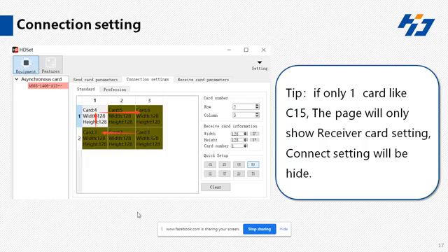As you can see, there is a quick setup, and quick setup four is clicked over here. This means that the first receiving card is on my right-hand side at the bottom, and the second receiving card is moving towards the left of the first receiving card, and then above it is the third, then the fourth receiving card, and after the fourth it is the fifth and sixth. So it is very easy to figure out how you have connected. Just assume you are in front of the screen, or just assume you are at the back of the screen, and you can select these quick setups one by one to check which is your quick setup.